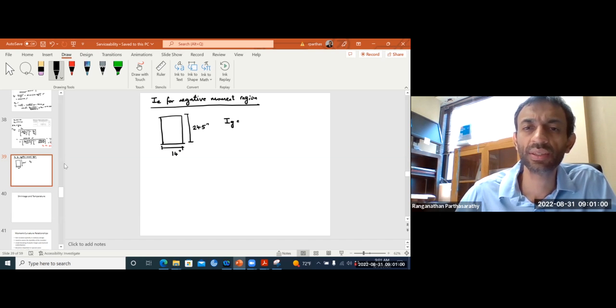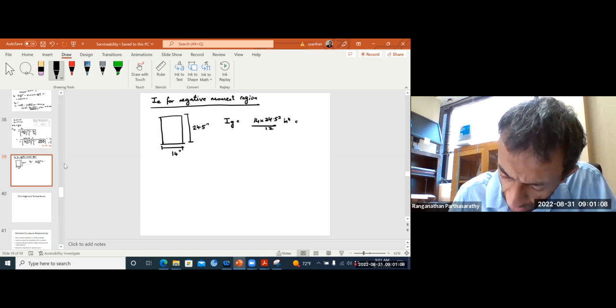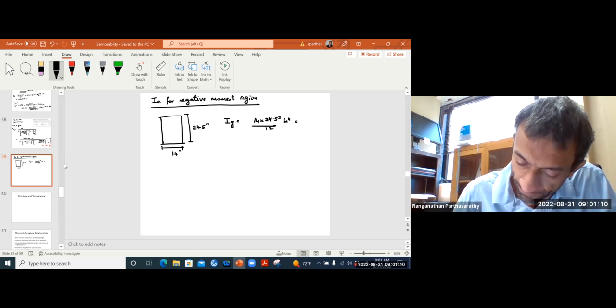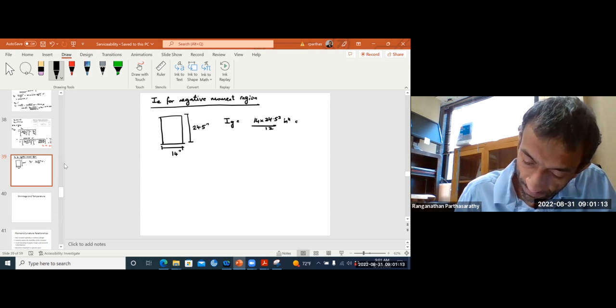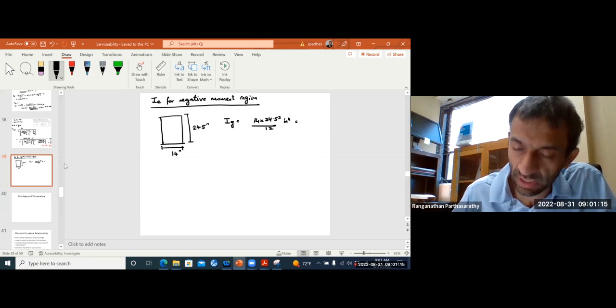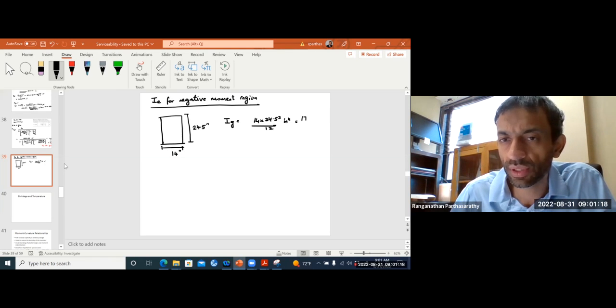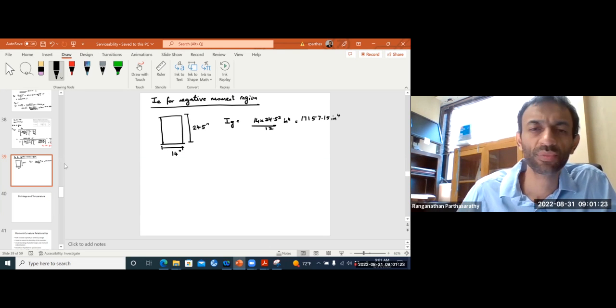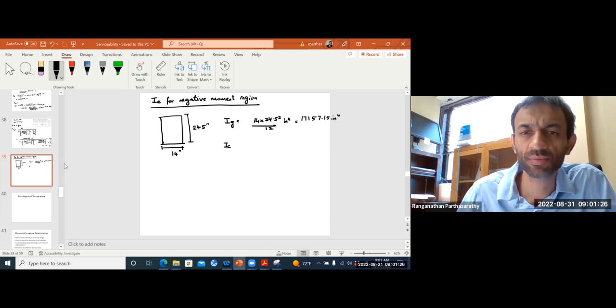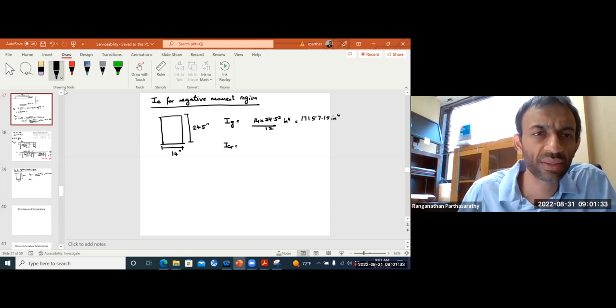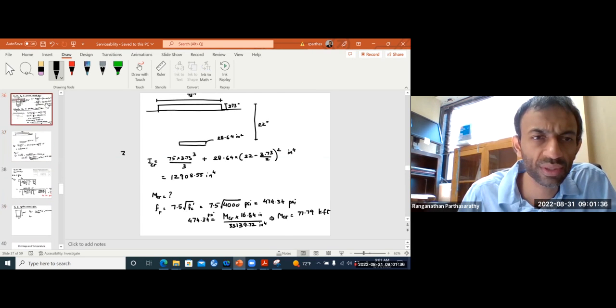Your IG is BH cubed by 12, which is 1715.15. What's your ICR? What is your cracked section? I think it's given to us. Let's use it.